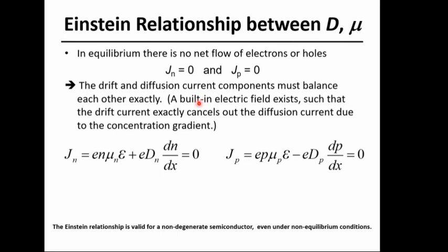We will be talking about how we obtain that. If we're talking about, for example, silicon, we said it's 0.7 volt, that's the built-in potential. So with the built-in potential, that means I didn't apply an external potential to the system. So in that case, the net current due to electrons will be zero, and the net current due to the holes will be zero.